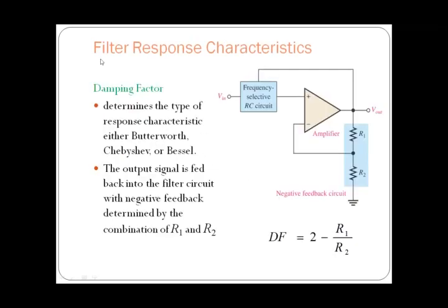And coming to the filter response characteristics, we are going to discuss here the damping factor. The damping factor is going to determine the characteristics of the response of the filter, that is, whether it is a Butterworth filter or another type of filter will be determined by this damping factor.